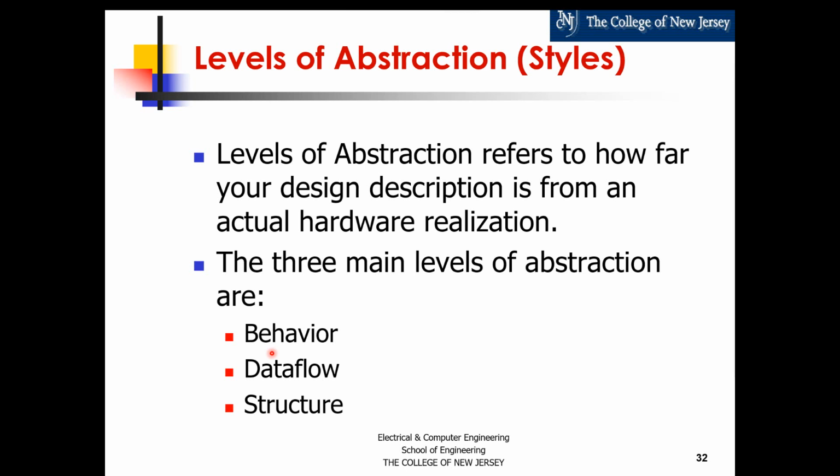And the examples that we use to conclude this presentation, which we'll do probably in 2 weeks from today, are going to be key for that. You have to have behavioral, synthesizable Verilog for your design. Now for the test bench, you want to be all behavior, because you're not going to synthesize your test bench. You're not building the test bench. You are using the test bench to test what you are building, what you want to synthesize. So that's an important distinction.